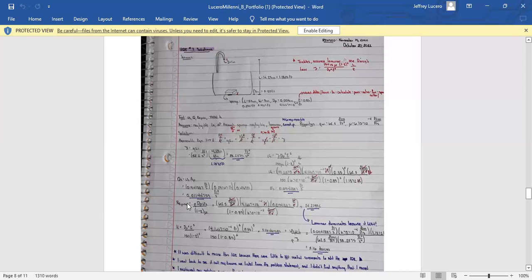The Re_p is calculated by density times diameter porosity times velocity over 1 minus porosity times viscosity. You get 24.21992. This is laminar flow because it is low. Laminar does dominate, which makes sense why we can assume laminar with Darcy's law. If it was too high, we couldn't assume Darcy's law.